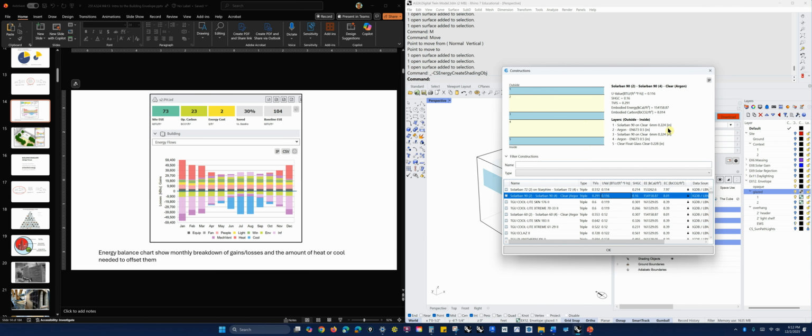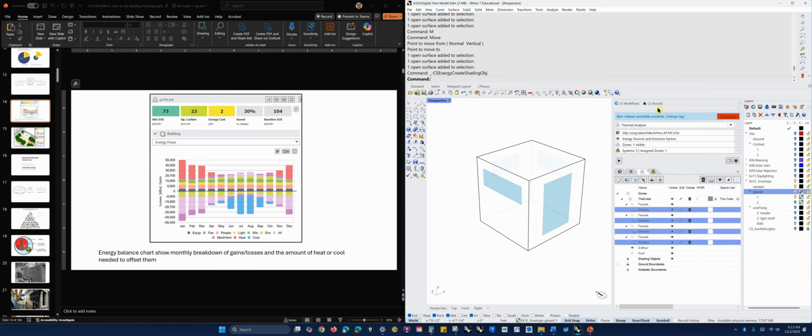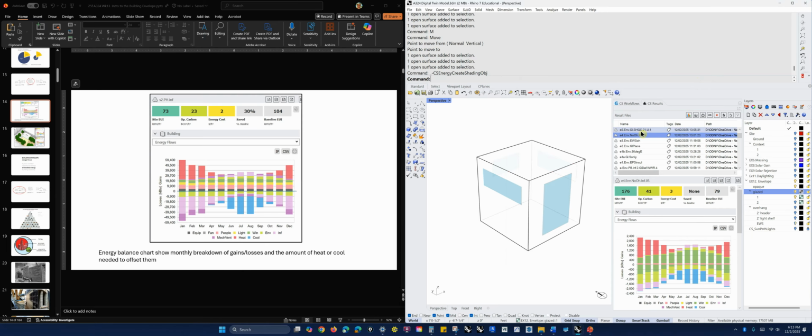Then we see this section here, just like we did for opaque envelopes, showing the glazing and talking about the properties. These are all things that you should be able to understand from what we've talked about this semester, so you should be able to intelligently choose a piece of glass, or just experiment and try some different ones. I was able to get this to go down by choosing better glazing, but again, I won't be able to emulate that in my physical model.